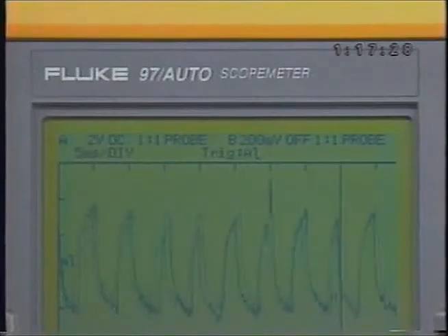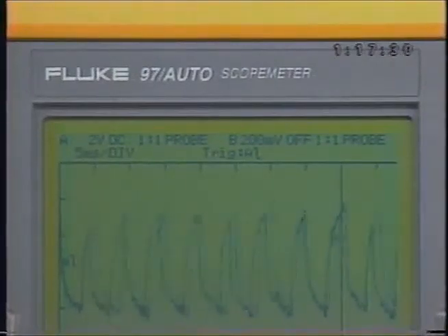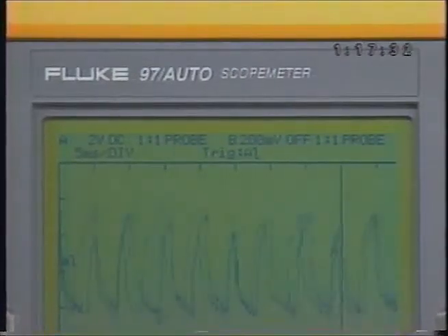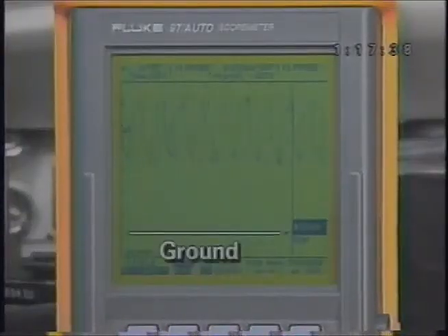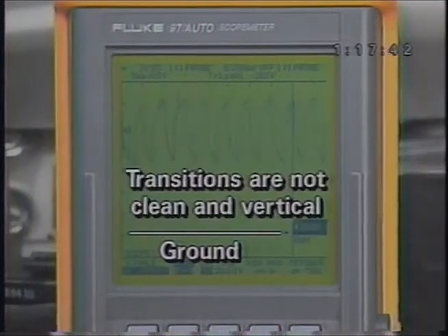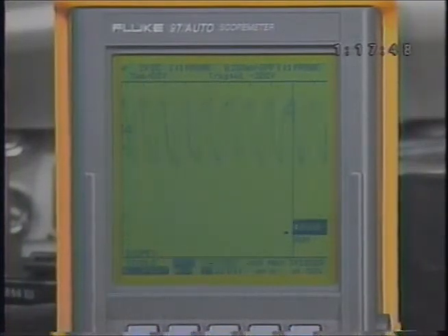If the voltage levels stay above 11 volts, but the idle speed won't remain low enough, look for a vacuum leak or a misadjusted throttle plate. With this type of waveform, the signal doesn't always go to ground, and the amplitude varies. The transitions aren't necessarily vertical and may be sawtoothed or curved by solenoid inductance. The setup for this exercise will be useful in the shop for diagnostic procedures. Save it to Setup Memory 6.